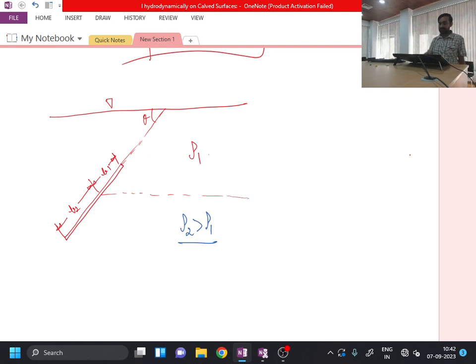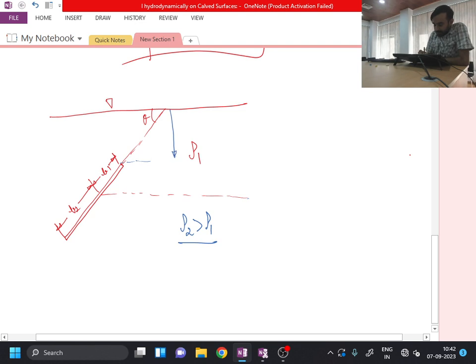Okay, but this is the stable situation. So if you have this type of situation, then how do we determine the forces which are acting on the body? One point is obvious. Say this point is submerged through a certain height S. If the outside pressure is P naught, then at this point my pressure will be P naught plus rho g s. Say this is the pressure.